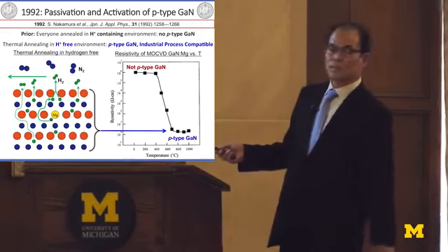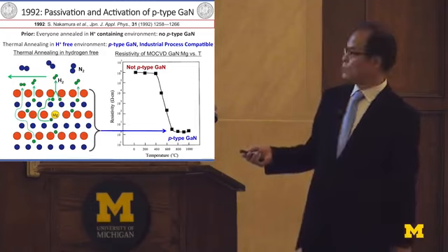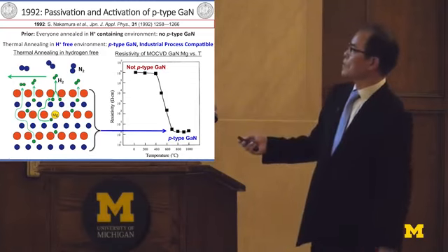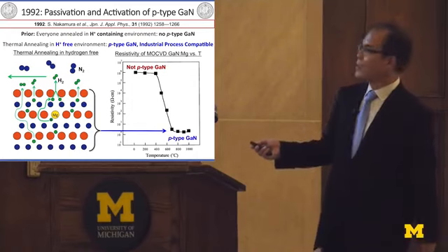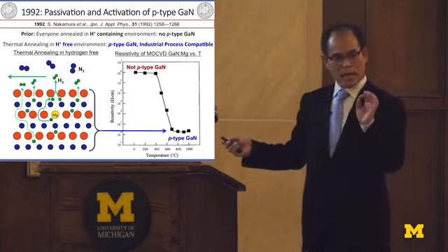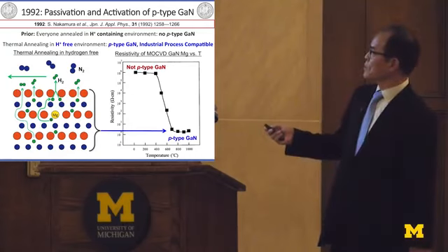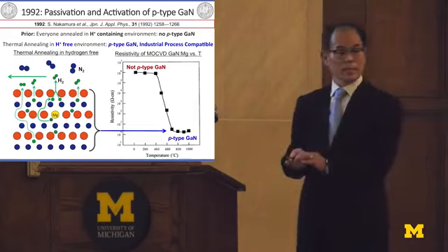The problem with P-type gallium nitride is we always use magnesium to make it. Magnesium should act as an acceptor. But always the resistivity became semi-insulating when we doped magnesium. But Professor Akasaki, they just accidentally irradiated the electron beam. They got a low resistive P-type gallium nitride, but they couldn't understand the mechanism.